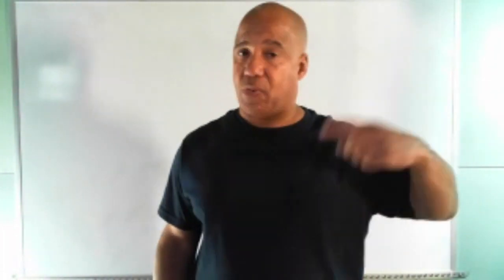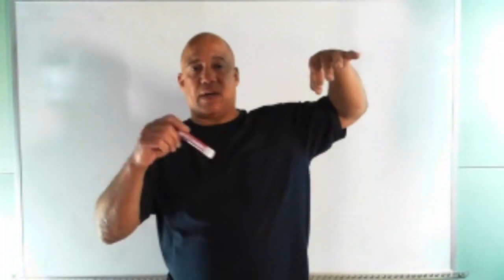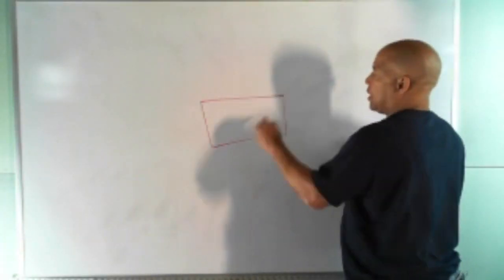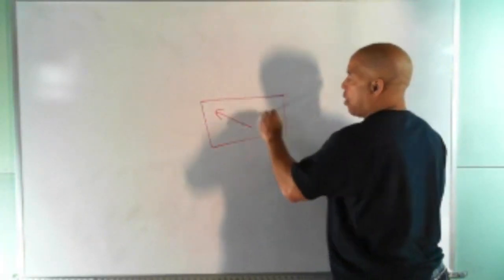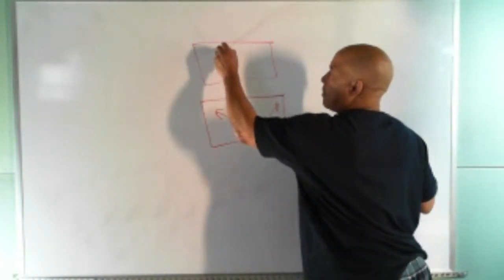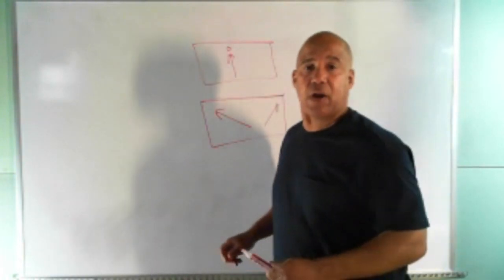I showed you a video where there was a guy who had 3 coils of wire. He had a coil that had 1 loop of wire, a coil that had 10 loops, and a coil that had 100 loops. He took the wire and the magnet and hooked the loops up to a current meter. The meter was interesting because most meters park the needle on one side, but in this meter the 0 was right there, so the needle can move to the left or to the right, indicating the direction of current.